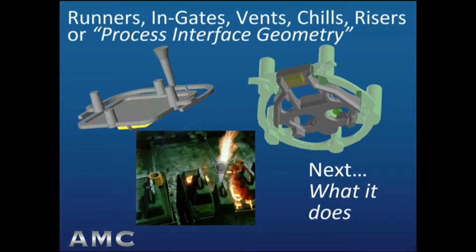The casting, as in the upper left, although it needs to be vented as well, has a pouring temperature of probably 1325 Fahrenheit, and so therefore the immediate combustion of mold cavity binder systems and creating gases quickly with large volumes of pressure is not nearly as great.